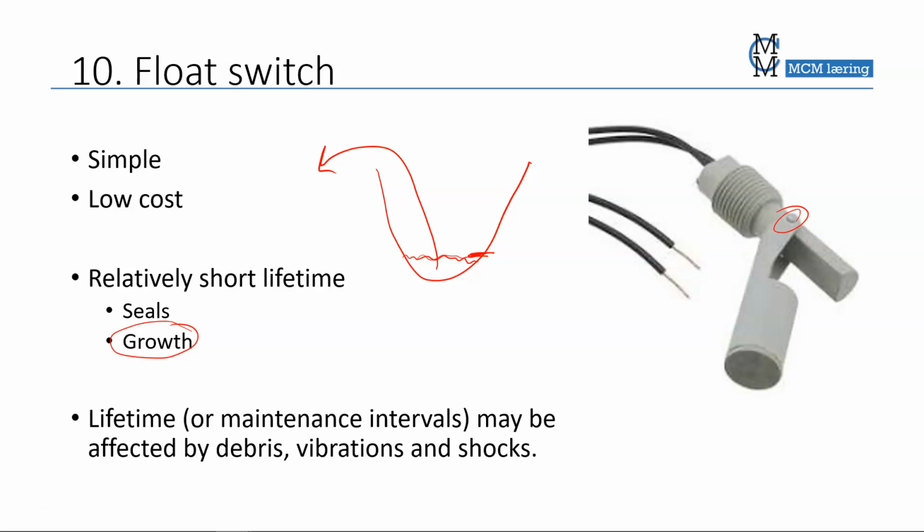But then again, often they are very easy to change for a new one, and there is of course no calibration needed, so the change is really easy. Example with the boat bilge again: change that level switch for a new one, and the pump will start on exactly the same level, since it's attached at the same place as the last one.